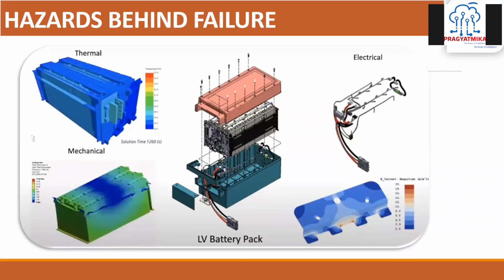Like for one cell, if you have maybe one centimeter of wire, and for the last cell module you have taken a 20 centimeter wire, there is a 19 centimeter difference in your wire length, and there will be a difference in resistance because the wire has resistance. So more voltage drop can happen, and less balancing of the cell may occur at the extreme parts. These things are considered while designing the pack.